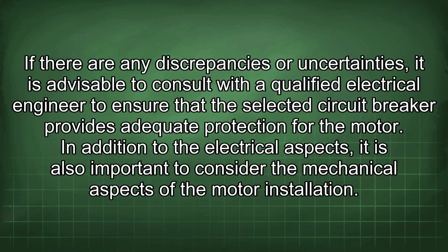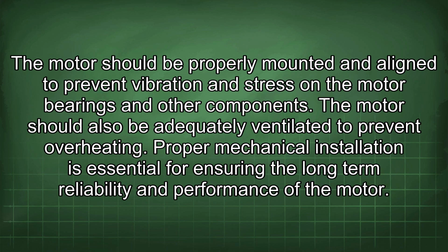In addition to the electrical aspects, it is also important to consider the mechanical aspects of the motor installation. The motor should be properly mounted and aligned to prevent vibration and stress in the motor bearings and other components. The motor should also be adequately ventilated to prevent overheating. Proper mechanical installation is essential for ensuring the long-term reliability and performance of the motor.